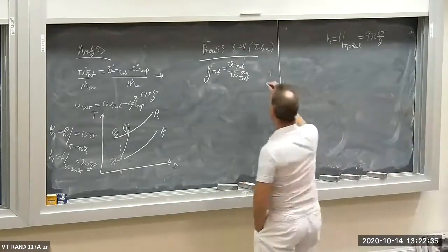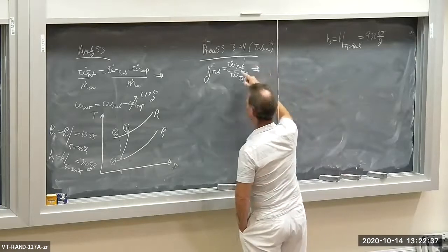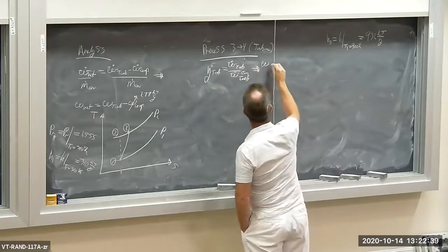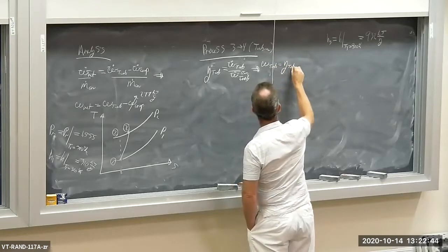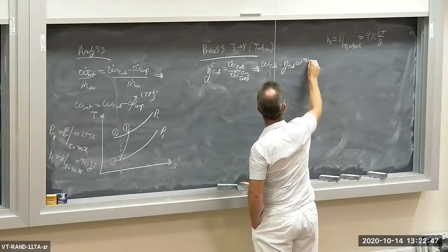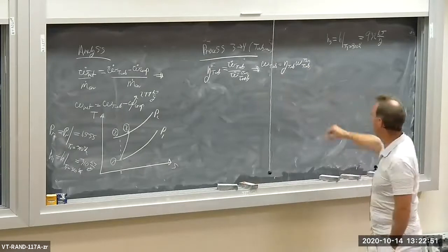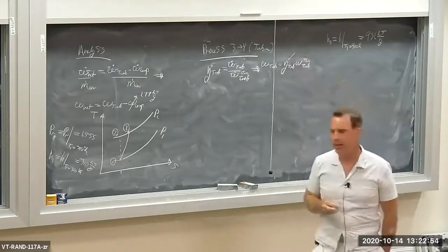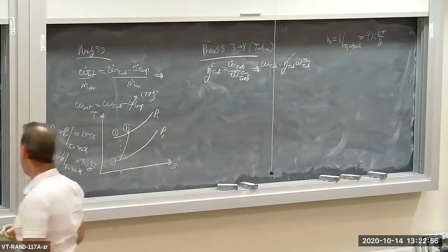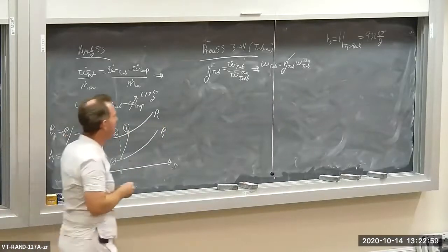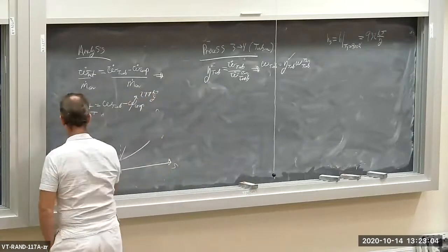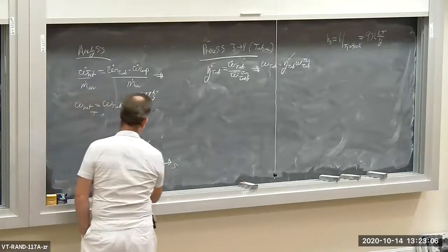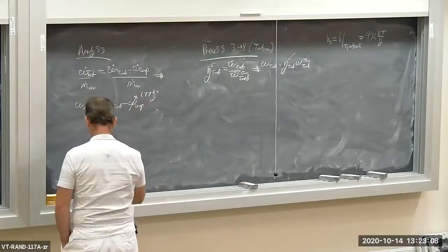In other words, dividing by m dot, W turbine is equal to eta turbine times the isentropic turbine specific work. Now, I know the efficiency for the turbine, it's 86%. So now I need to evaluate the isentropic turbine work. So let me put up the TS diagram for the turbine.